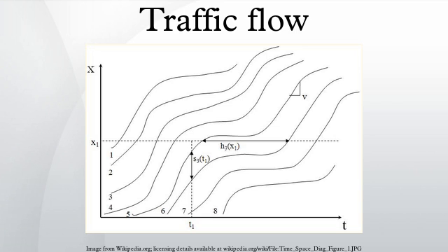Generally moving bottlenecks are caused by heavy trucks as they are slow-moving vehicles with less acceleration and also may make lane changes. Bottlenecks are important considerations because they impact the flow in traffic, the average speeds of the vehicles. The main consequence of a bottleneck is an immediate reduction in capacity of the roadway. The Federal Highway Administration has stated that 40% of all congestion is from bottlenecks.